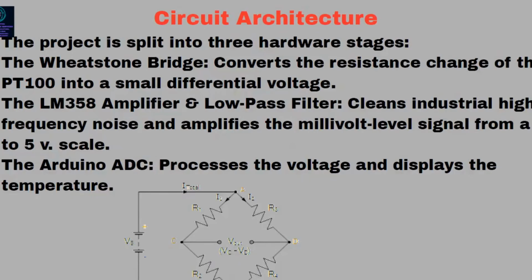The project is split into three hardware stages. The first is the Wheatstone bridge. The input signal is given through the Wheatstone bridge so that the voltage change at the point will also show up at the output on your Arduino board. It converts the resistance change of the PT100 into a small differential voltage.